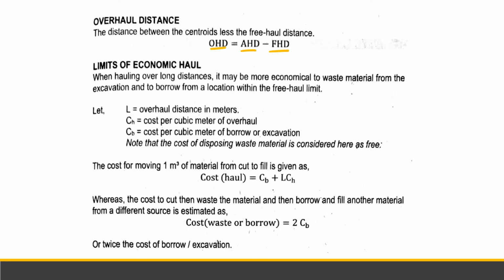And beyond that section is overhaul distance, meaning you will have to get soil to fill that part. So, limits of economic haul. When hauling over long distances, it may be more economical to waste material from the excavation and to borrow from a location within the free haul limit. So we still consider the economic aspects.